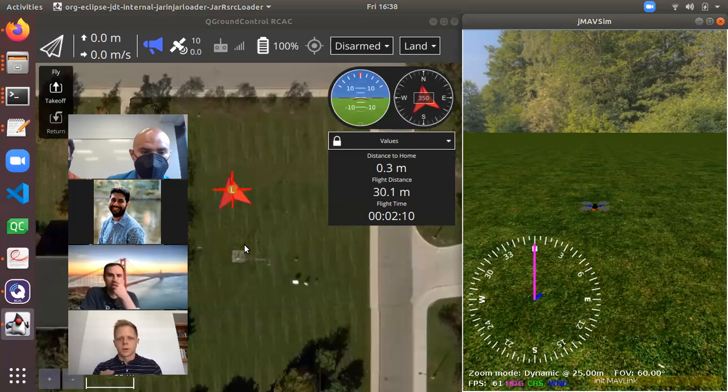Initially, when we were talking on Monday, I was thinking that with the waypoint publishing you could just publish the end goal and it didn't need those intermediate points. But it seems like you really do need those intermediate points along the path to where you're ultimately trying to go. We're still setting end goals, just in a manner that doesn't cause the quadcopter to overshoot. The interpretation is that we are issuing those waypoints in smaller steps at a slower speed. So they are smaller and also slower. That's basically it.